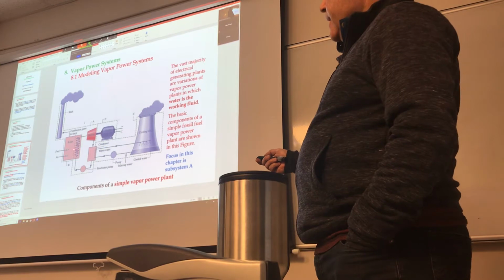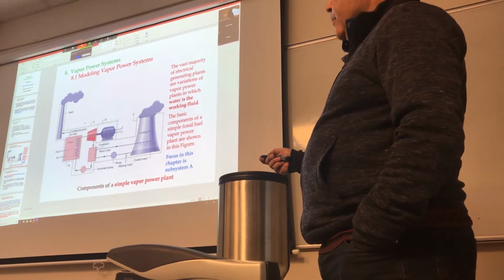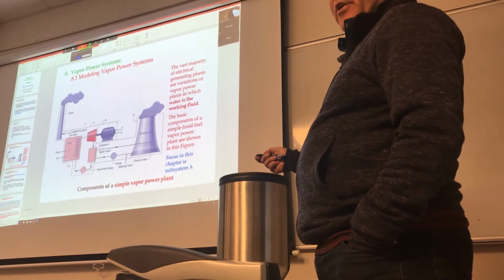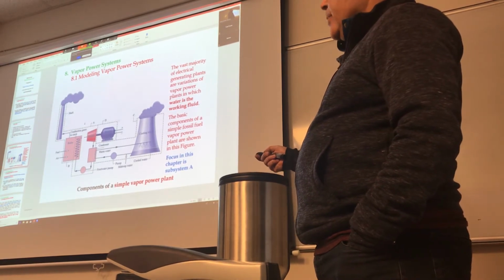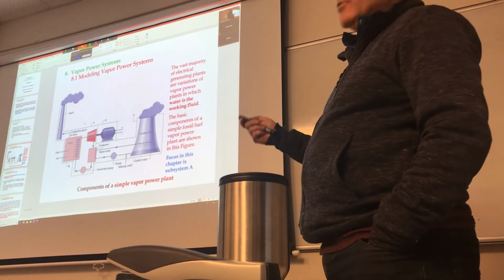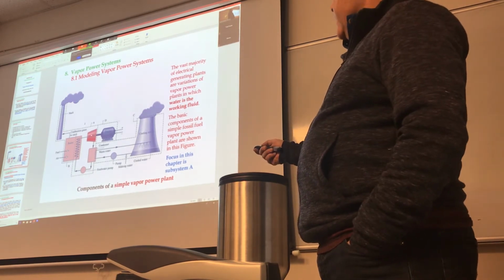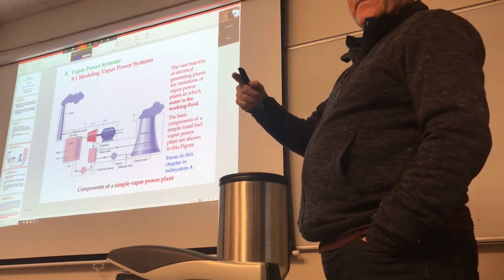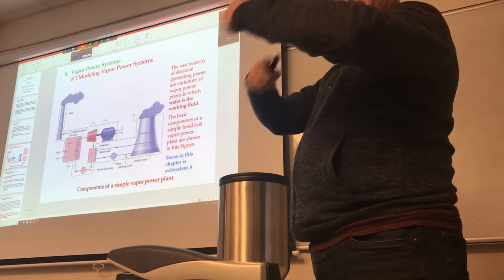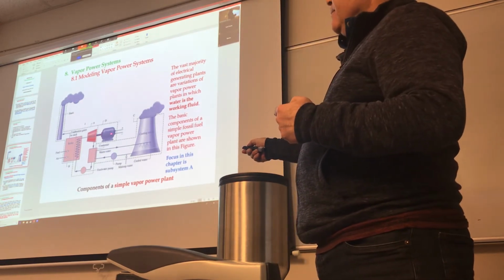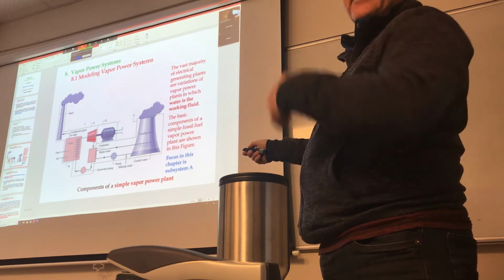And then this is a heat exchanger, so you're burning fossil fuel and adding thermal energy to your pressurized water, right? As it exits through here, it comes out at very high temperature and high pressure. As it goes there, it expands through the blades of a turbine and pushes against them. It creates a shaft that rotates, which you could in turn hook up to a generator and generate electricity.